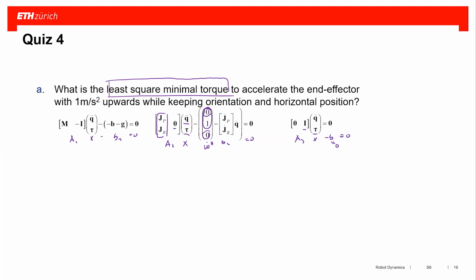Now what I have to solve is to make sure we optimize, we try to fulfill this task as well as possible while ensuring that this task and this task are fulfilled. And I have the tool for doing this. Either I do this continuous projection into null space, or I take a much better optimization toolbox that does consecutive least square optimization, and there you go.